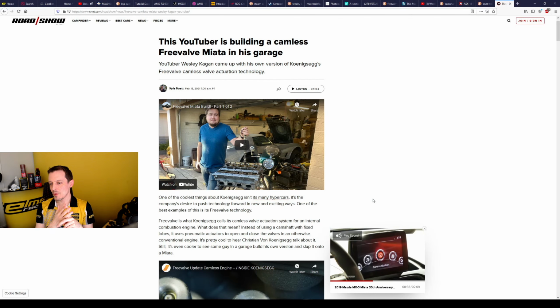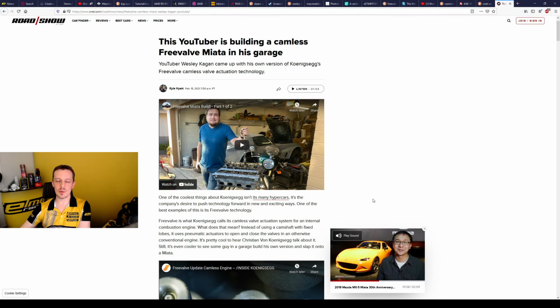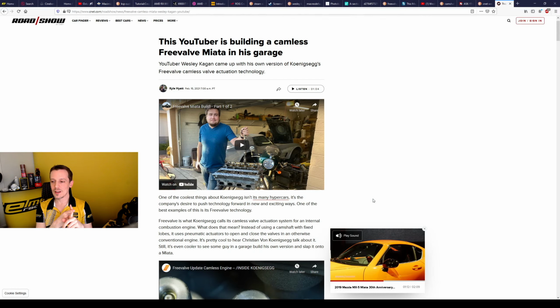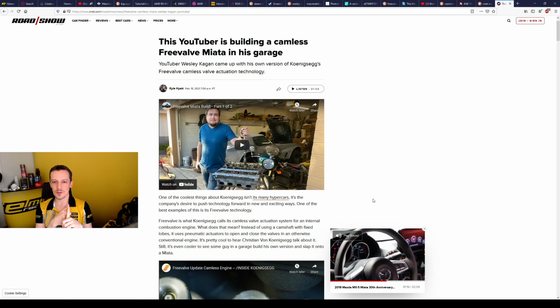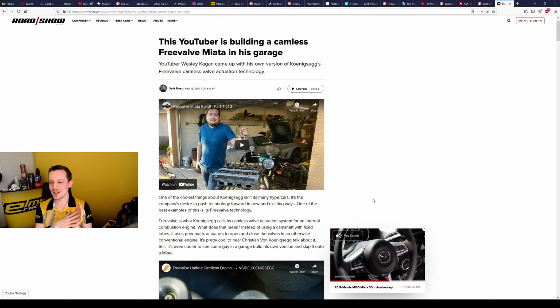Because I do remember them being quoted as saying that it is an electro-pneumatic hydraulic system. Of course, to operate with any kind of ECUs, electronics has to be the end control, but using really high forces and energy levels with electronics is not very practical. So that's why you want to use high pressure hydraulics or pneumatics.